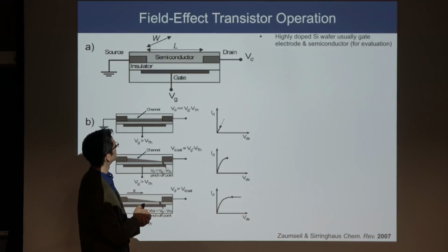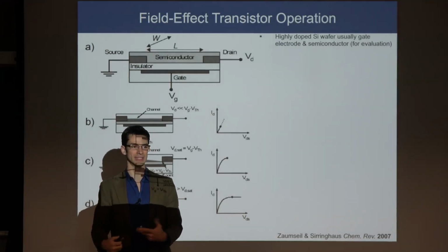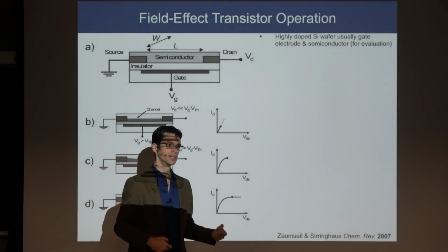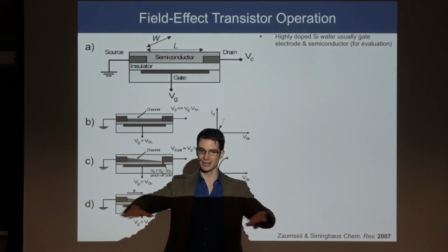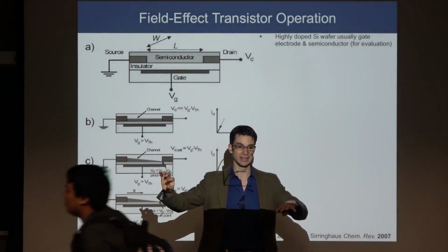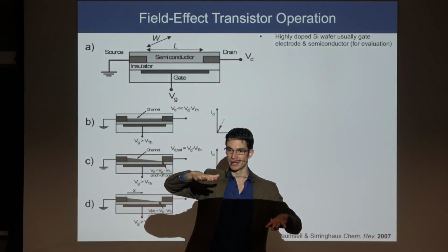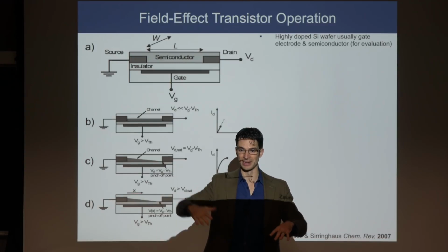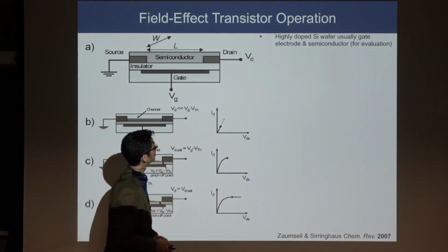In the case where you're testing silicon itself, you can start with what's called an SOI wafer, which is a silicon on insulator wafer, which is manufactured in such a way to give you a highly conductive substrate, then an insulating oxide film, then another semiconducting layer on the very top, and then all you need to do is apply your source and drain electrodes and you're good to go.